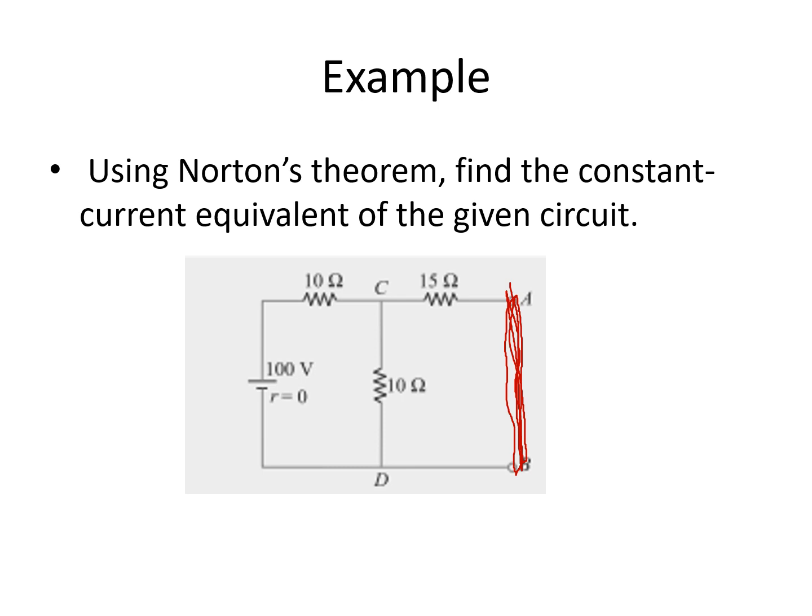Okay, so a while ago, the resistor in parallel with the short circuit was bypassed, but this time it will not be bypassed because of the 15 here. So if I have a current here at point C, it will divide. Not all of the current will flow across this short circuit here because we also have a 15 ohm resistor. Okay, so we have to short A and B.